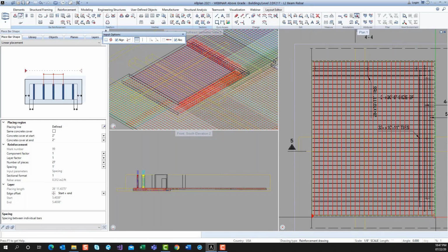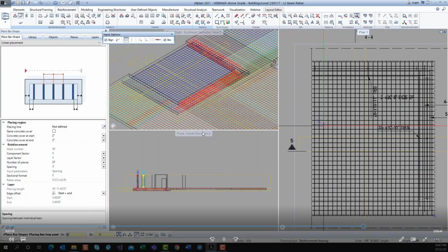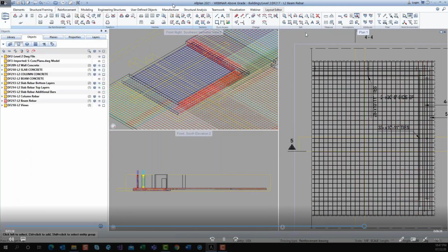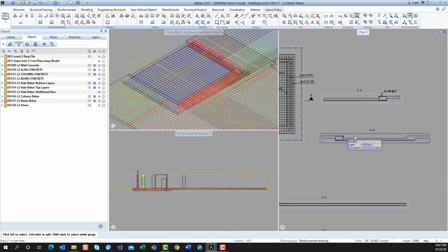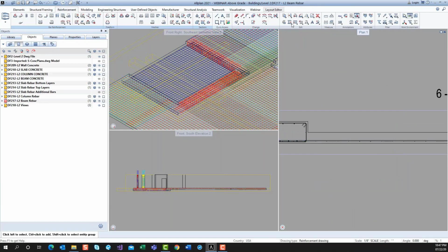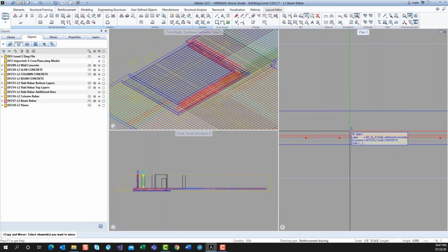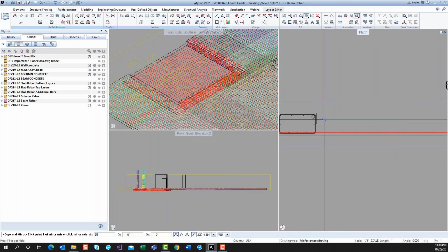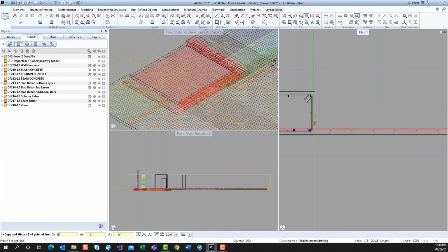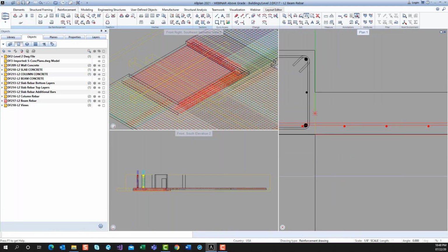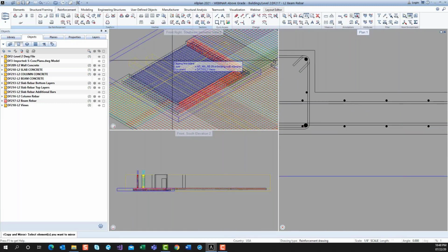So I got all the bars in here. So you can see I've got this. Now again, using the CAD functionality of our software, I don't have to redraw these. I can do my copy command. And you'll notice that now I have the 3D open, as I'm doing this, information is showing up in 3D. I'm going to copy around a midpoint, an implied midpoint, by using our intuitive tracking. And I can mirror those up instantaneously like that. It's created all my layers over to here.